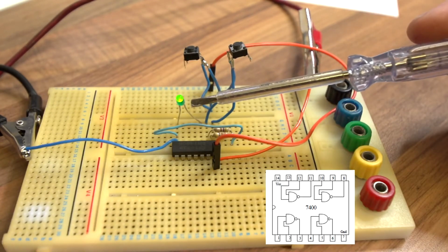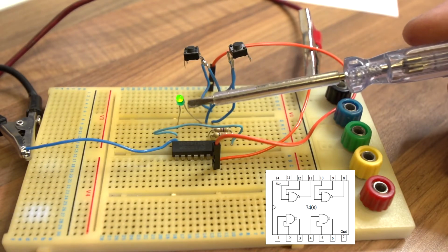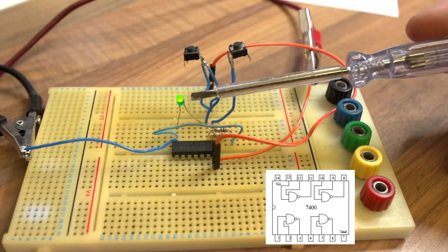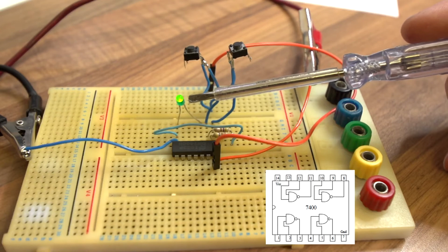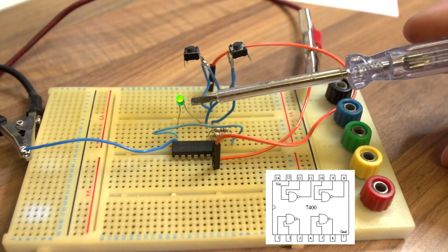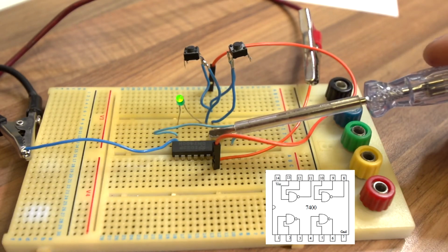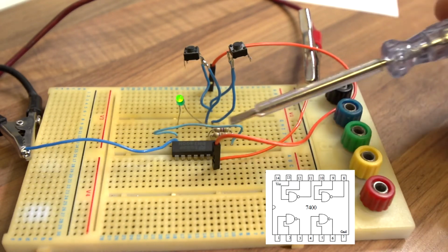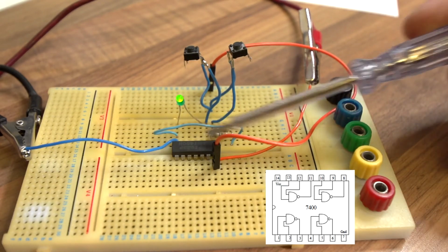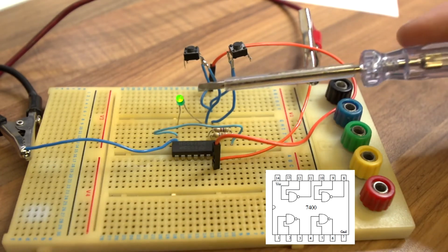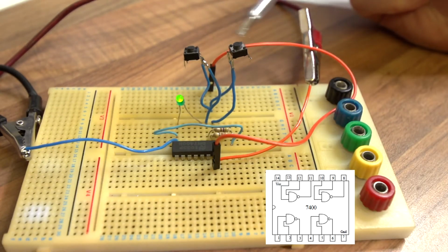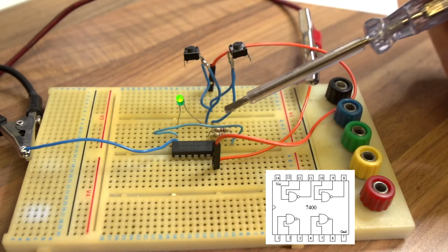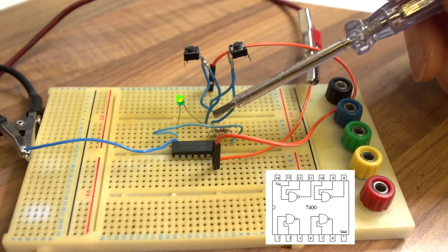Got a little LED here, which is actually a 5-volt LED. It has a little internal resistor, and that allows us to put 5 volts straight across the LED without destroying anything. So it's designed to work with logic levels directly, and that connects to the output of one of the 4 gates. I'm only using 1 for this experiment, and the LED is connected to the output of that first one. I've got 2 switches, little micro switches, clicky switches, tactile switches as they call them, and they're connected to the 2 inputs of the gate, input A and input B.